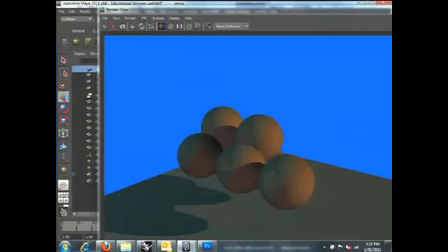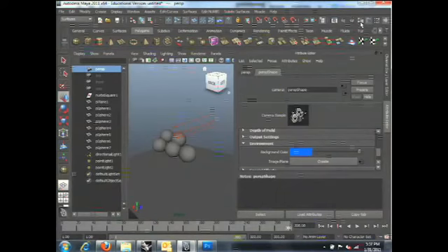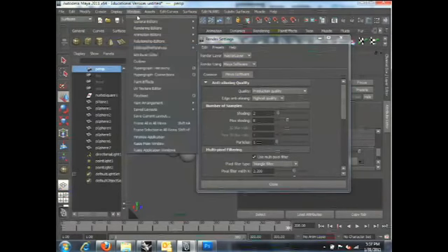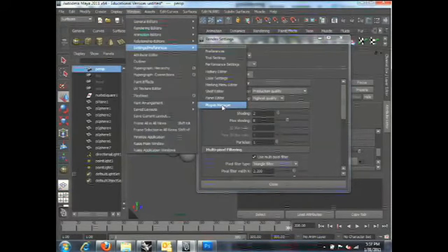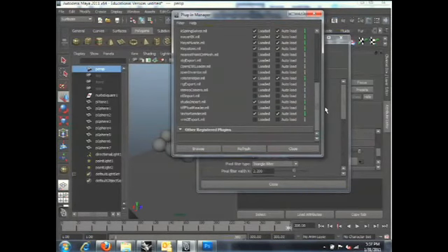All right. I will show you one more thing about Maya rendering. Besides software rendering, there's another rendering type, which is Maya vector rendering. Again, if you don't see this option show up, you have to go to the plugin manager. Just make sure you activate the vector render plugin. Okay, this plugin should be checked.